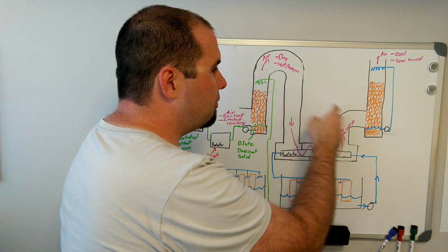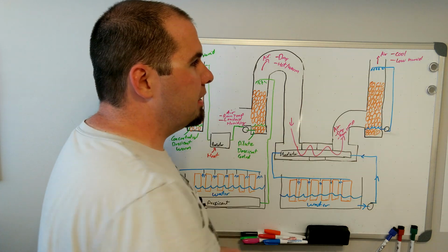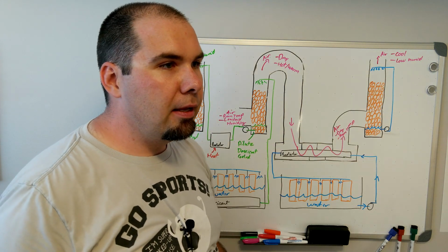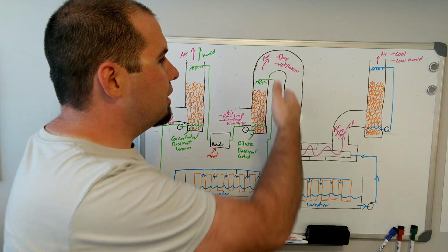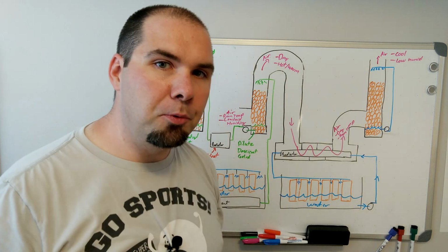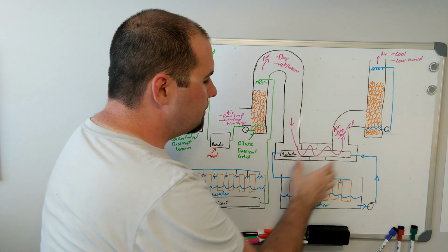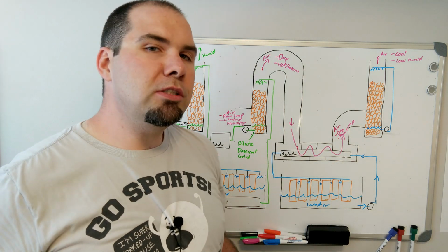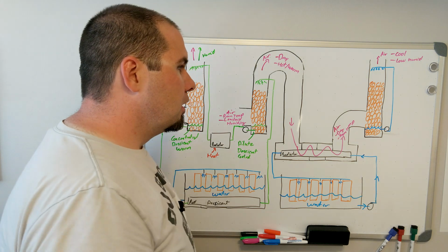So, I mean, if we just put it directly into one of these right away, the net effect is we've got this warm, hot air. We cool it and add humidity. We're back to square one. We need to cool it in between and cool it to, say, room temperature.